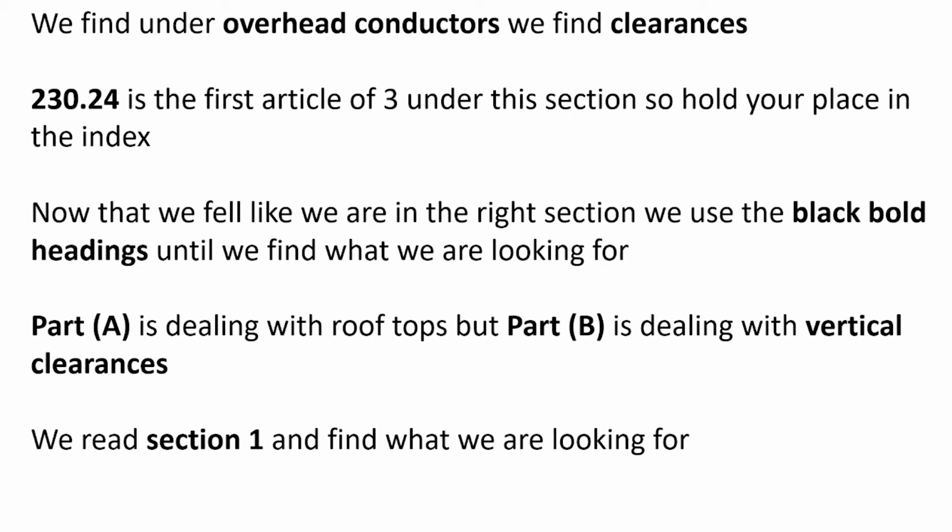It's looking for electrical entrances above sidewalks accessible only to pedestrians, measured from final grade. So this is exactly what we need. And the voltages do not exceed 150 volts to ground. So we're good there because we have 120 to ground, but 240 only across the two phases. So section 1 is what we need to select from, and we select 10 foot.